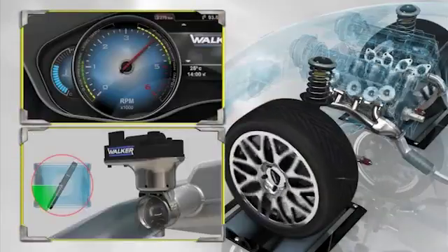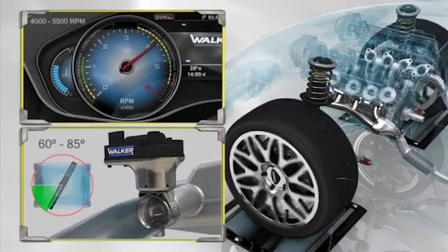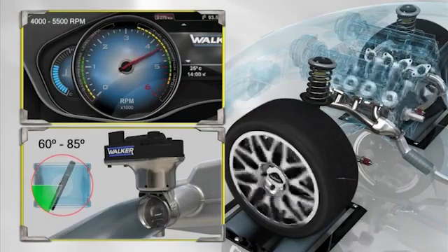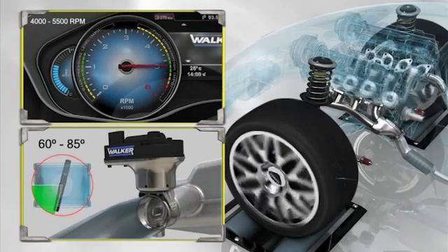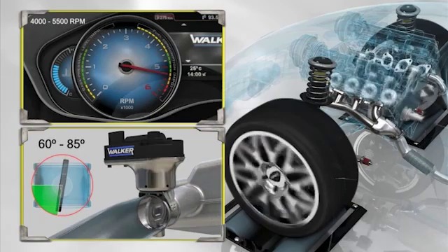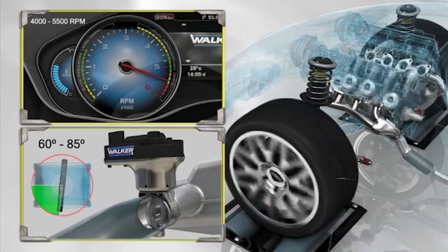When the vehicle is operating at increased load conditions, i.e. at high speed and on all cylinders, the flow of the exhaust gases will be maximized, so the valve is completely open to enable the gases to pass with the minimum back pressure.